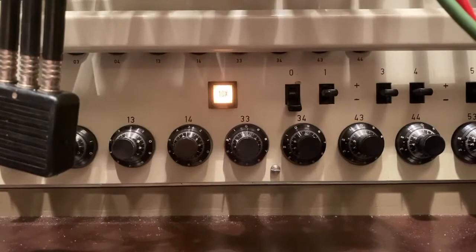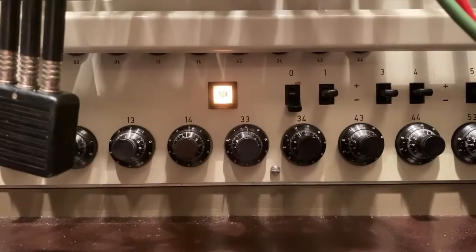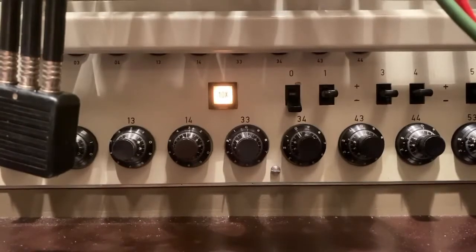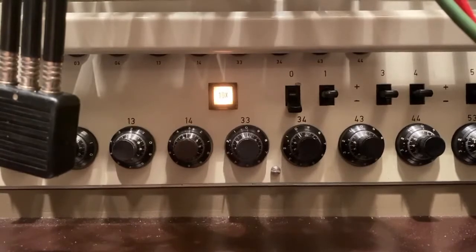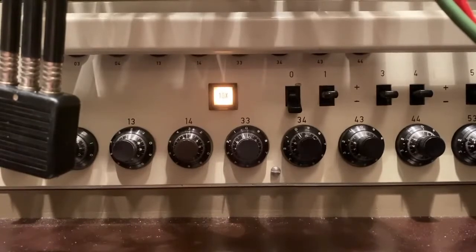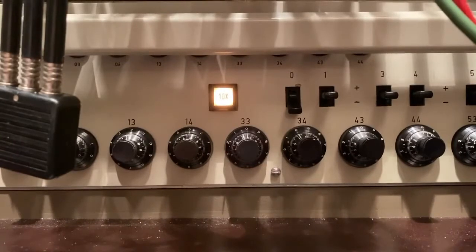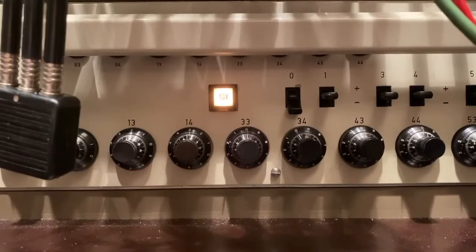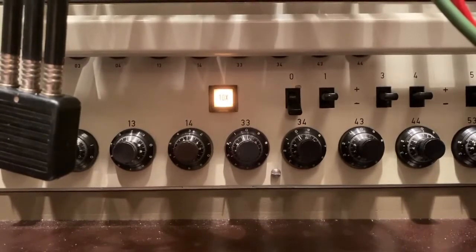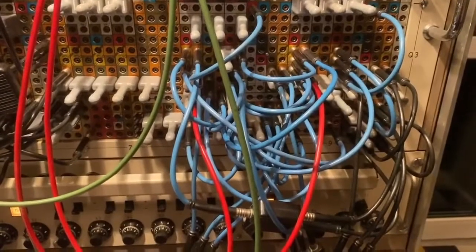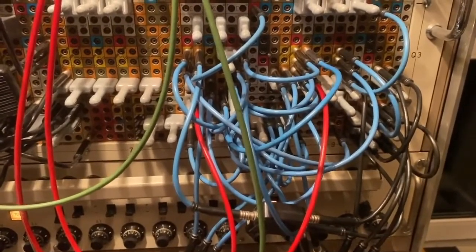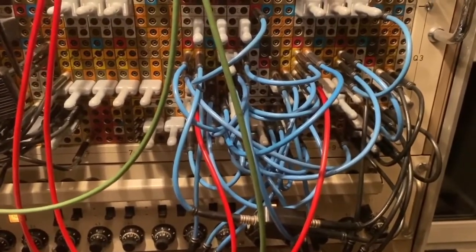So if you patch, for example, all integrators within a computer setup to 100 times the normal speed and depress this key, the integrators will run 1000 times faster than real time. So you can span a pretty large amount of time scales just by selecting which capacitor is being used in your integrators. I've also prepared a second sub-program, so to speak, which is a Lorenz attractor in this case.